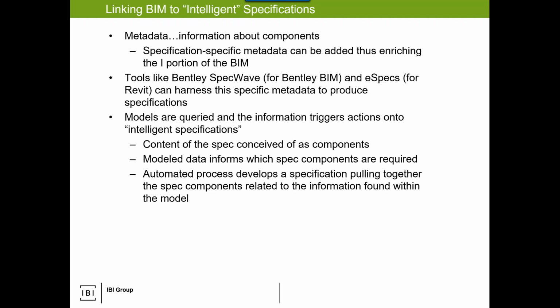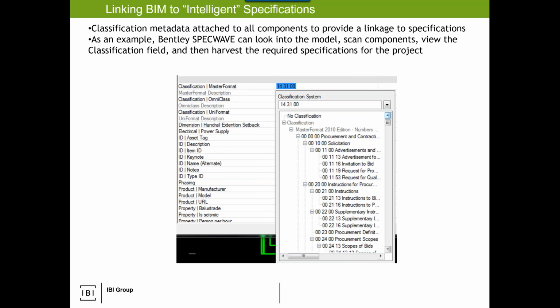And then it gets even more complicated. So imagine the exterior wall. So the wall is made up of gypsum wallboard, maybe there's concrete block, maybe there's brick on the outside, there could be damp proofing, there could be an air barrier, there could be sealant, there could be flashing, there could be a parapet, oh my God, on the exterior wall, there could be maybe 15, 20 specs that apply to that. In Revit could tell me your exterior wall is wall assembly, whatever, here's all the components of it, here's your spec. That's what I'm talking about here with linkages to specs.